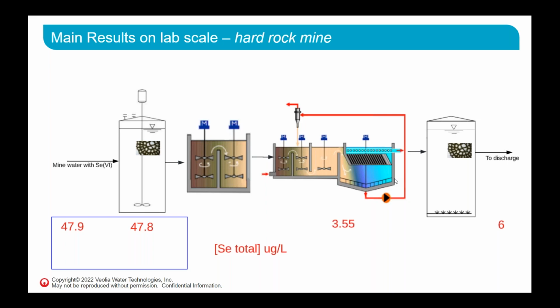We measured the total selenium going into the denitrification reactor, or the reduction MBBR. We can see that there's no modification of the total selenium concentration, which is normal because there's nothing going in or out of the system that would explain more or less selenium. So this is a good start to see that we are at equilibrium right there.